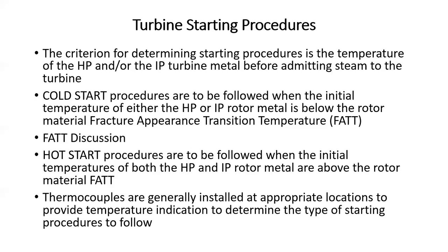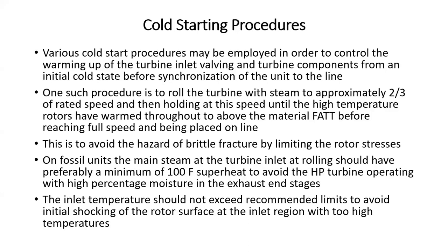knowing the measurement. Studies have been done. The Electric Power Research Institute has actually put thermocouples on the rotors themselves and put telemetry equipment to transmit out the signals. And so there's a good bit of information on knowing how to install those thermocouples so that they give the appropriate readings. That's not really an issue today.